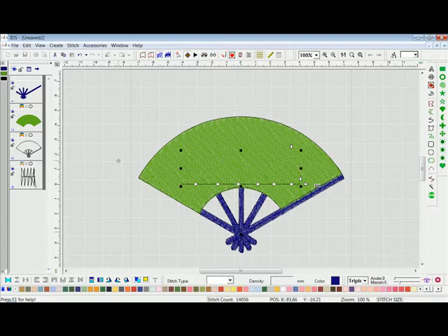In order to set my baseline, my cursor is now a crosshair. I will left click to enter the first point, left click to select. You can see I make it a point, and that outline is now highlighted in red. I then have to make a second point for my other endpoint, left click, and as I do that, I can move my cursor over the top and it will turn blue, or the bottom and it will turn blue. So I have two possible text paths that I can choose from.